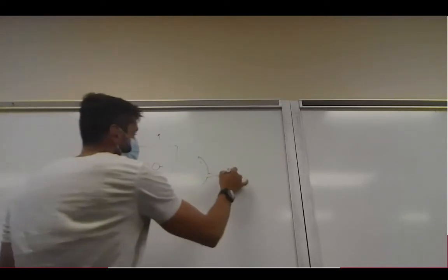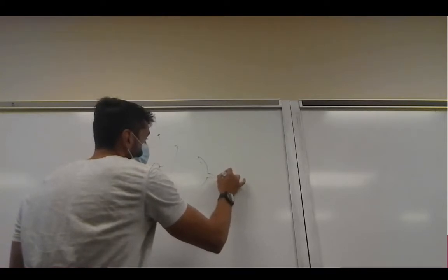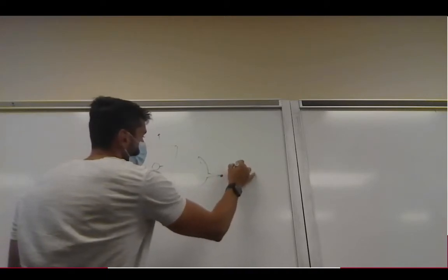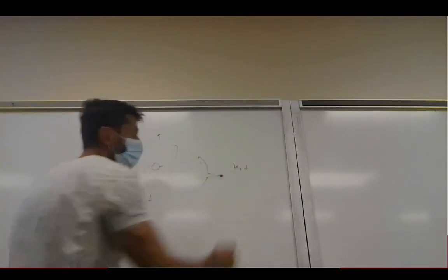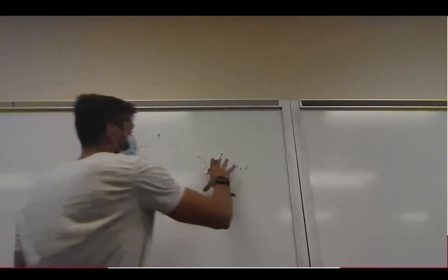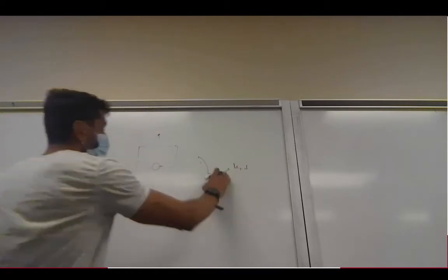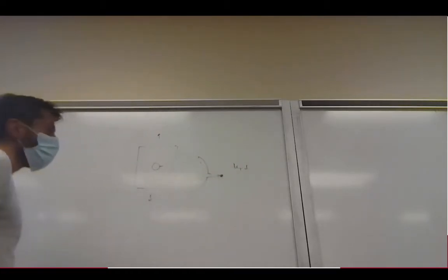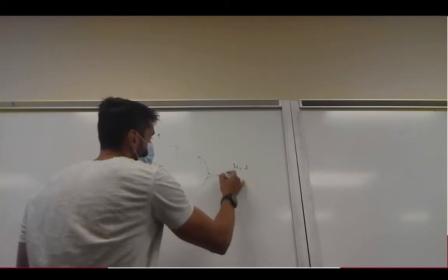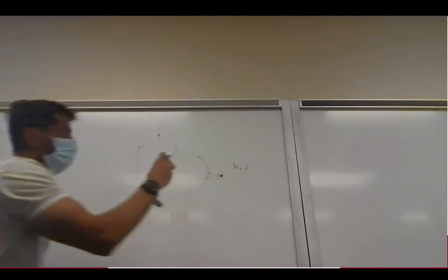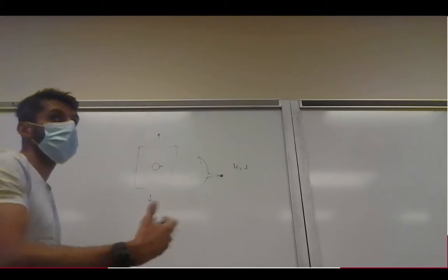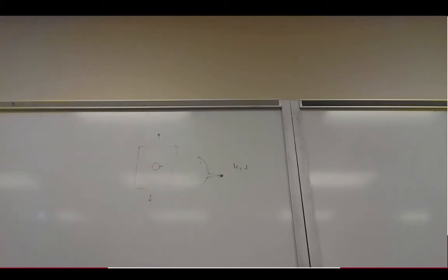So what you do is you cut a hole here at this location. Even though you increase the hole, the overall KT factor, the stress concentration, can go down. So you should postpone the crack propagation a bit more. And of course, on a material or molecular or grain level, what you can also do is locally harden it by straining it in a certain way. So then it also becomes a bit more difficult for the crack to propagate. That's totally different than what we're talking about here.